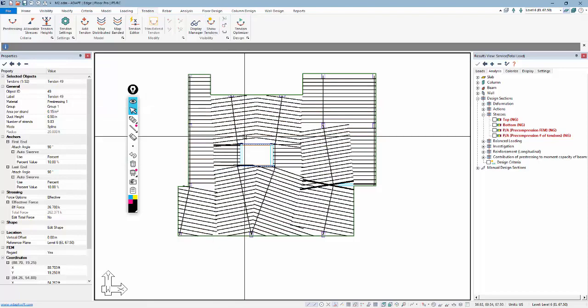Okay, so let's talk now about, we're going to just again assume that our tendons have been worked out, solved. Once we do that, there's really two main areas of strength that we want to consider, and that might be punching shear, two-way shear at the columns, and also the flexural reinforcement in the slab. So we're going to first look at the punching shear.